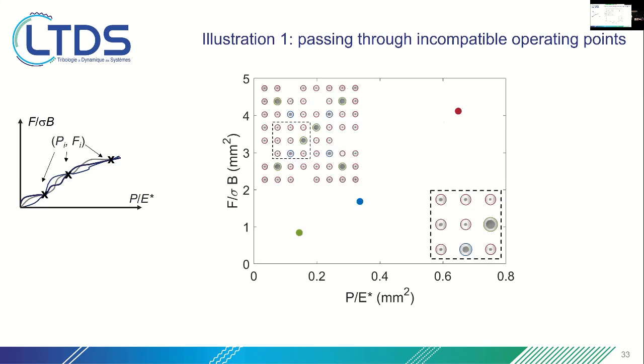Okay, this is a picture of the interface that we managed to design, with asperities here that you can see with our circles with colors, in the same color as the operating point that they contribute to reach. This is a zoom here in which you can see for each asperity its size, and also the black portion in the center is the real contact area for this specific asperity. So with this design, in black is a predicted friction law, the one we target.